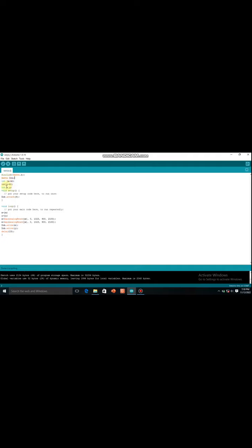And we initialize 2 variables, x and y, which we are going to use here. In our void setup, like I told you already, if you are creating 3 servo motors, you make sure you have 3 different objects, because each of them has its pin on the Arduino. So for the servo motor I created here, dop, I attach it to pin 9.